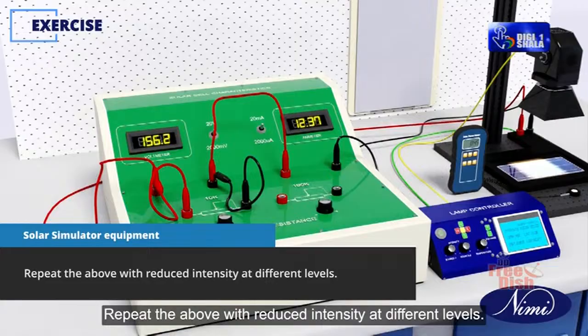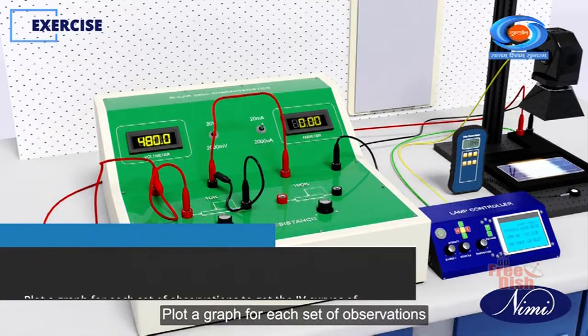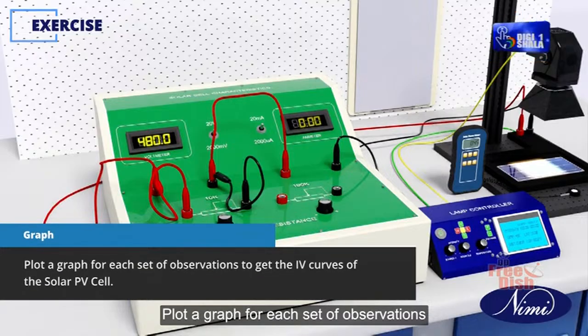Repeat the above with reduced intensity at different levels. Plot a graph for each set of observations to get the IV curves of the solar PV cell.